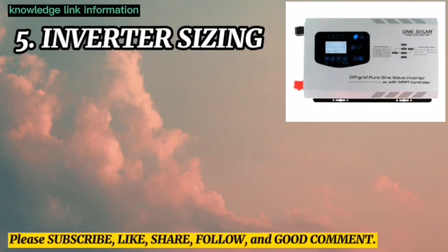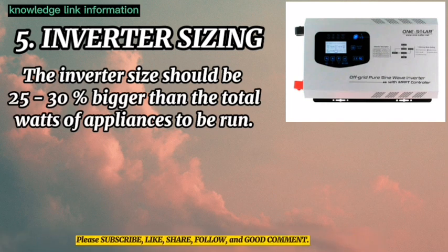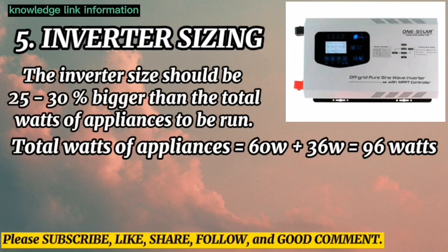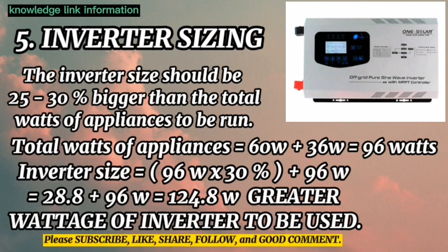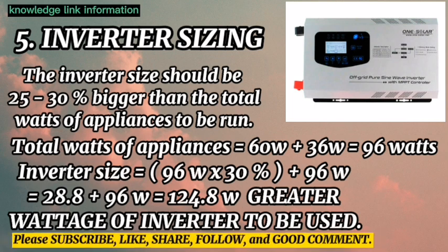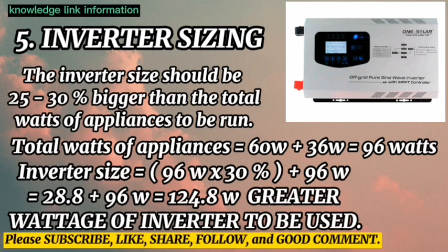Number 5. Inverter sizing. The inverter size should be 25 to 30% bigger than the total watts of appliances to be run. Total watts of appliances is 60 watts plus 36 watts, which is 96 watts. Inverter size is 96 watts times 30% plus 96 watts, which is 28.8 plus 96 watts, is 124.8 watts or greater wattage of inverter to be used.